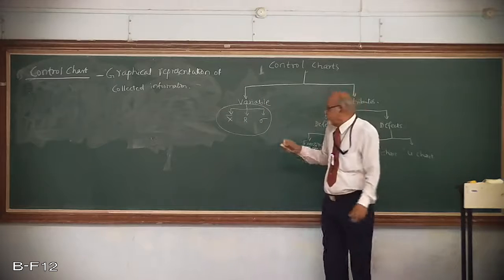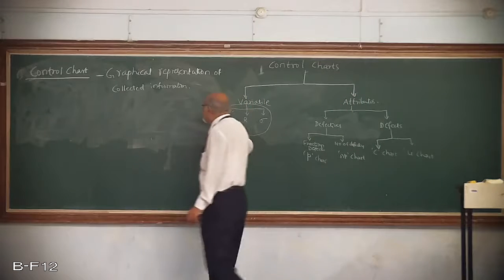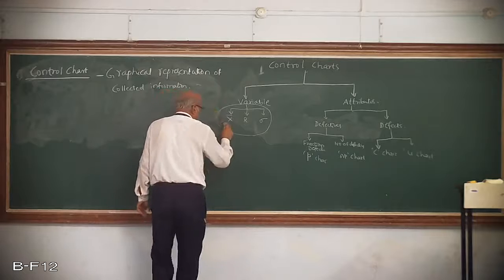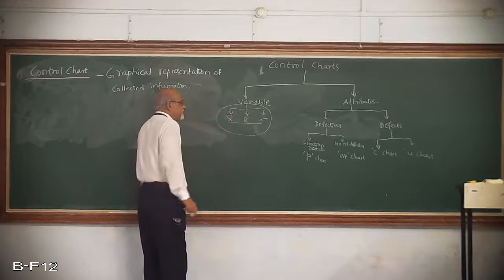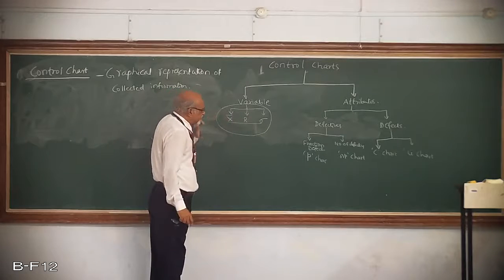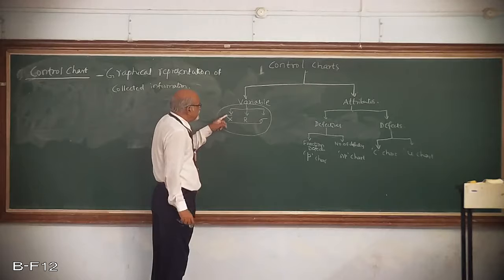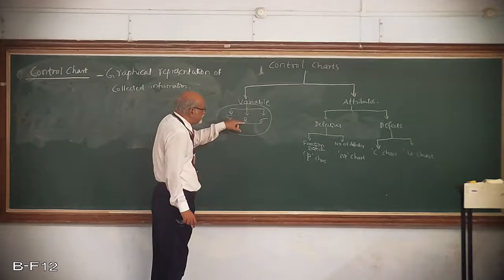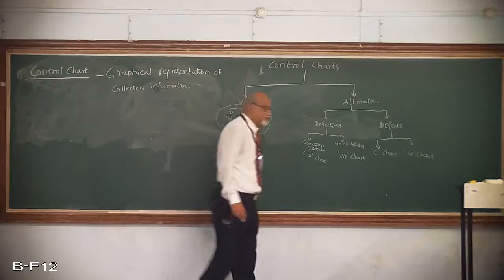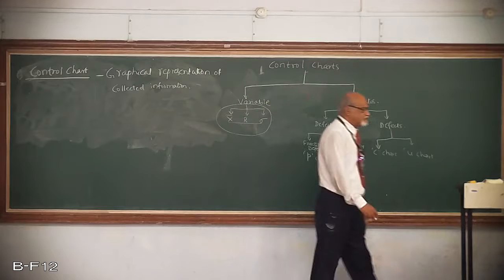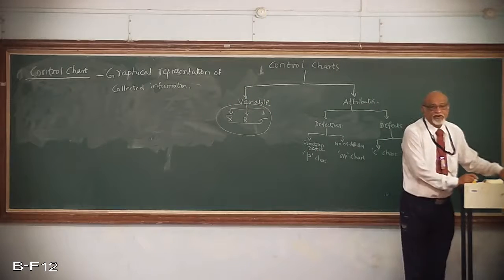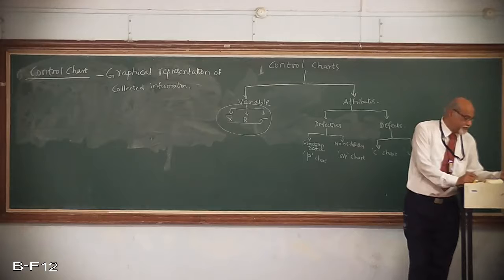Now let me limit this unit to these things. But try to understand, I cannot use it independently, X bar chart only, R chart only, sigma chart only. No. In control charts for variables, they have to be used in pairs.